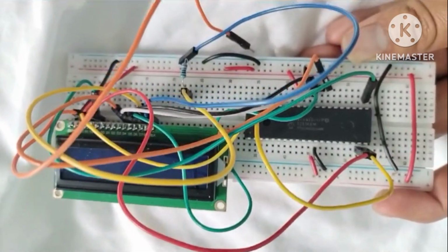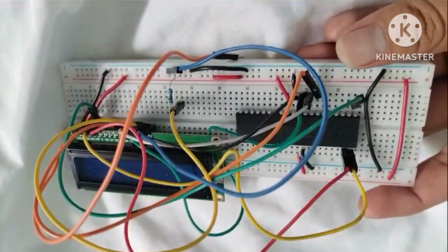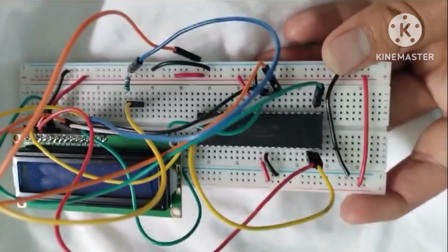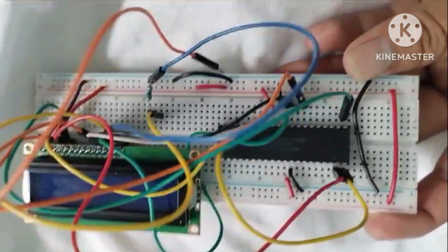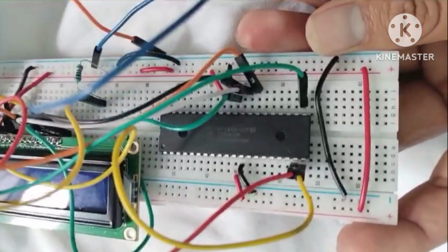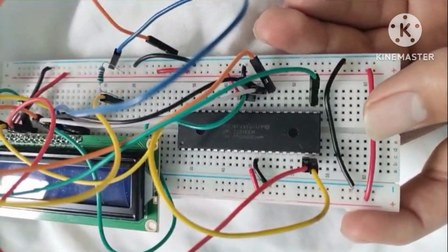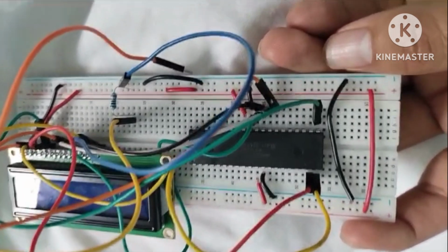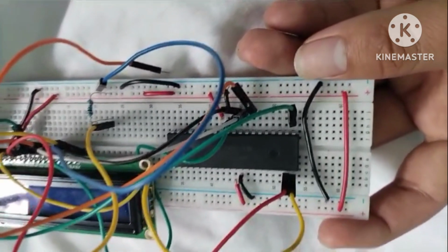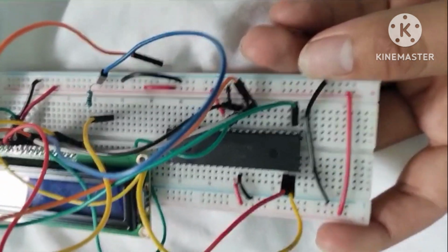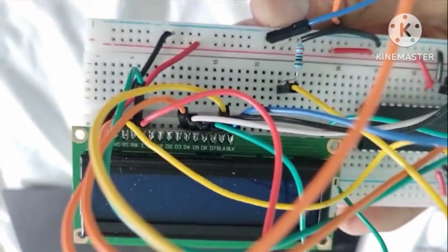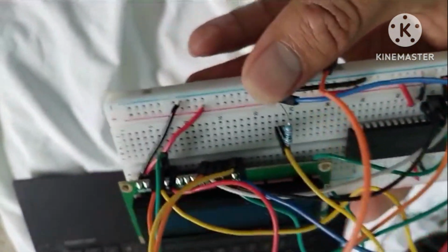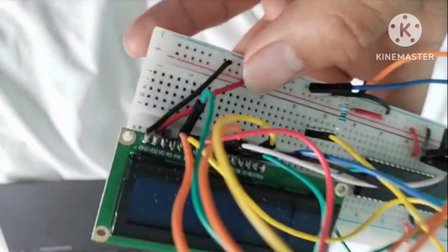I will explain the connection of the code to use 2 lines, which is practically the same as the first one. First, the PIC must be powered with the pins 11, 12, 31 and 32, where 32 and 11 go to positive. After this, the LCD needs to be connected with ground and 5 volts.